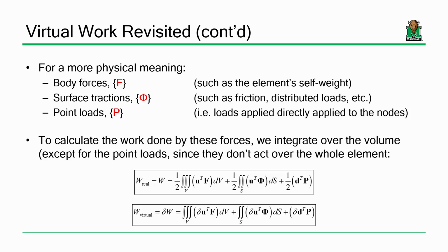A surface traction, I'm sorry, I'm a civil engineer. The easiest way I can describe a surface traction is if we're looking at a pile foundation. Pile foundations get their resistance from the tip capacity, but also, and more critically, from skin friction. That force is applied along the pile. You take a pile and you drive it into the ground, and that pile is resisted by the friction of the ground. That's where you get your capacity.